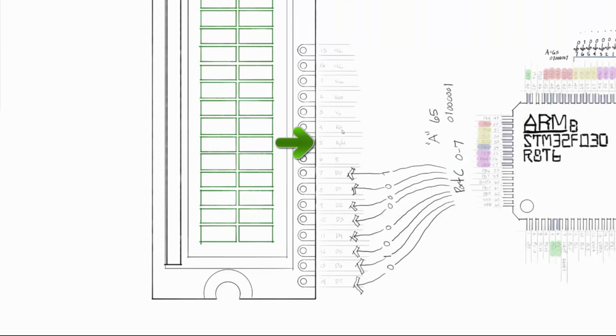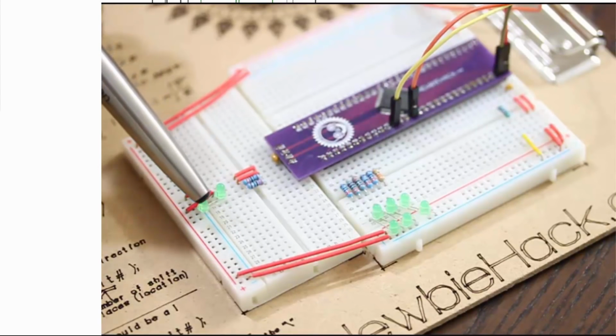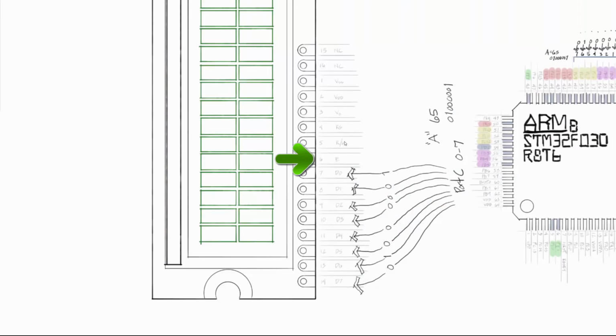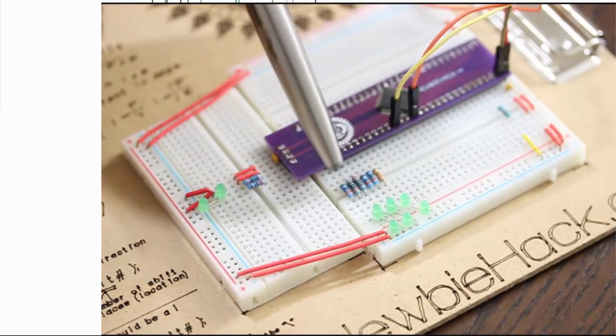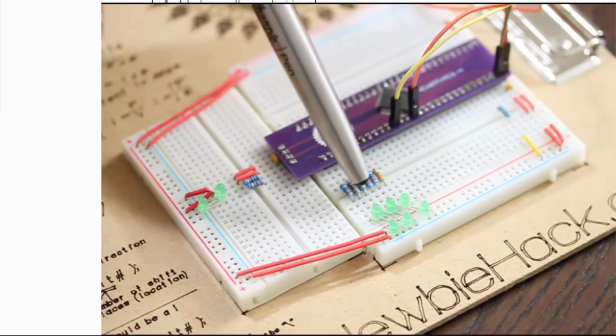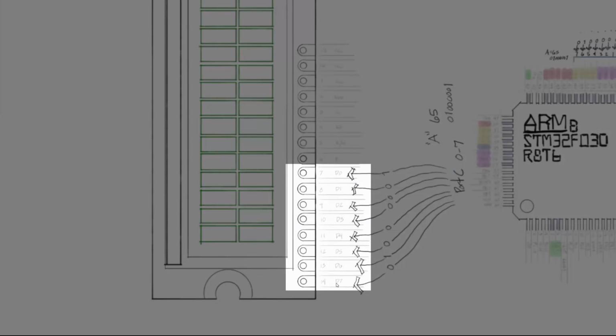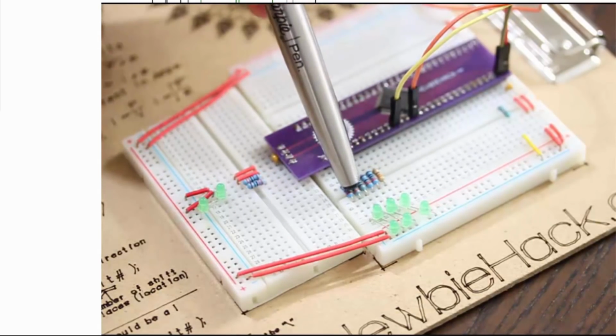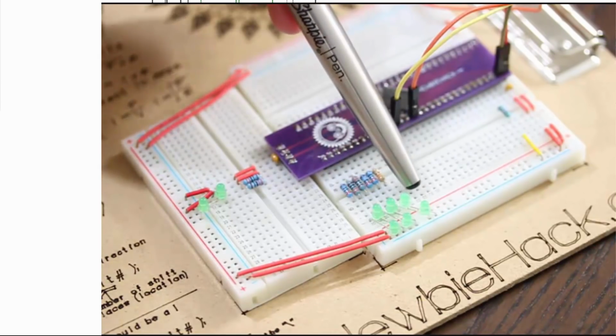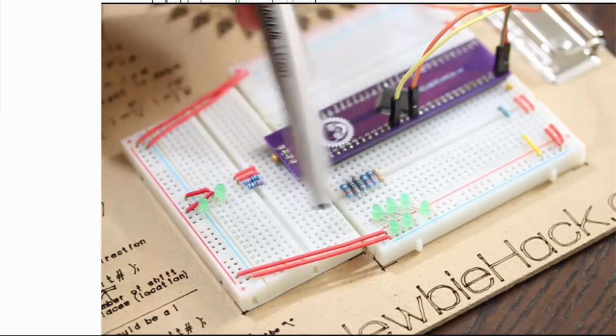The second one is the read write, so the read write would be the next LED. And then the enable would be the LED that's on this pin here. And then after that, we can have these pins from D0 to D7. We can have them along this side here. We'll just use some jumpers going to these tie strips.